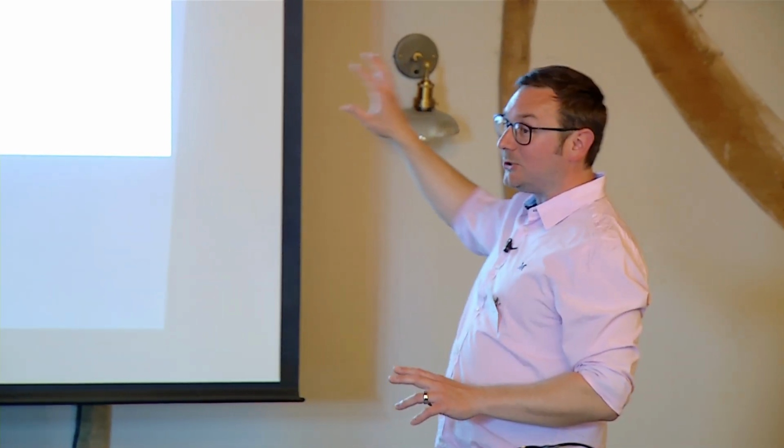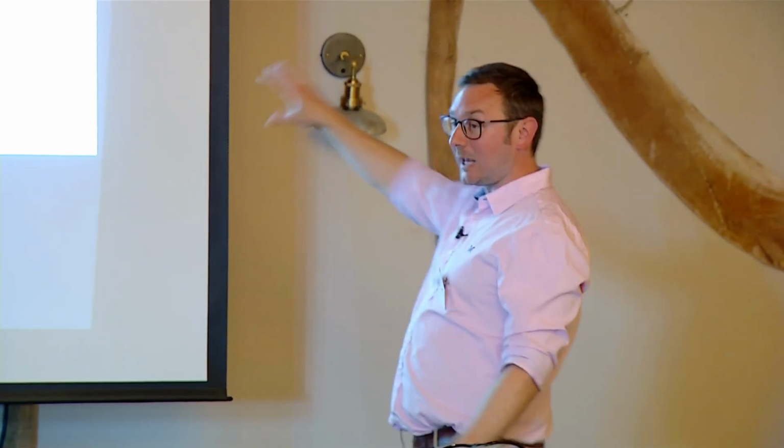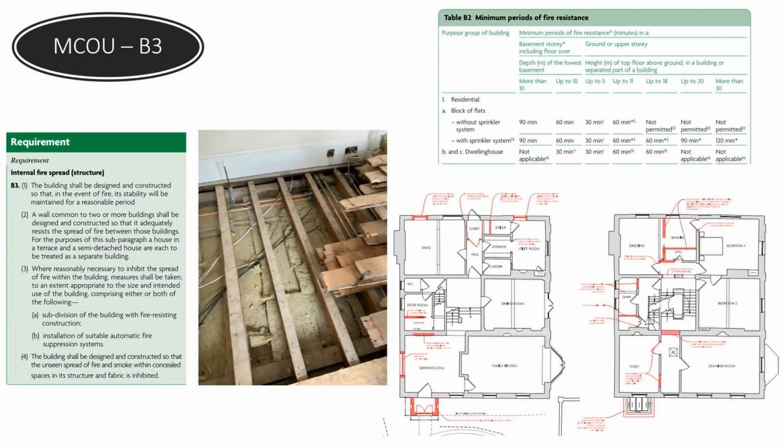Now, I promise I will come to your question. So, B3. Again, using a real example, this was the same project where we had a material change of use. Material change of use under 5A, B3 imposes a requirement. So this was actually a listed building. So the ground floor needed to have a fire resistance for those floor elements to the upper floors above.